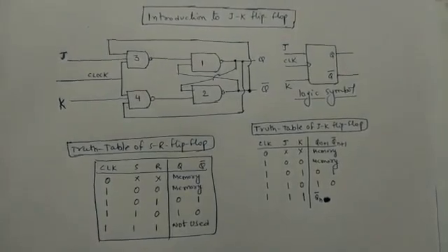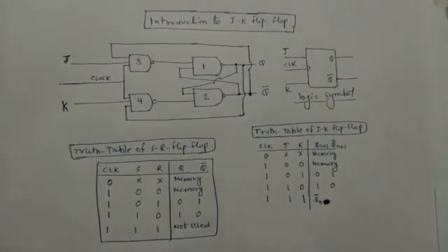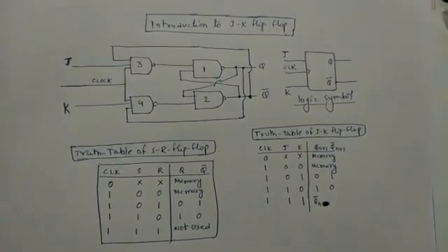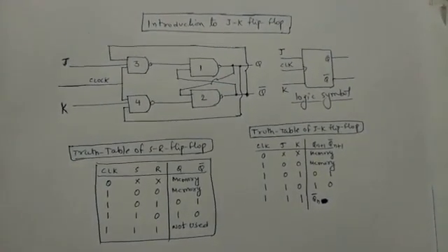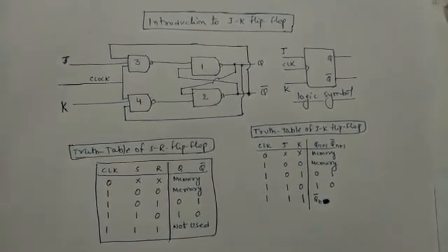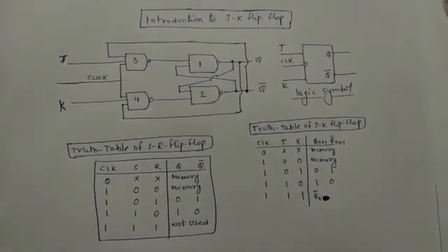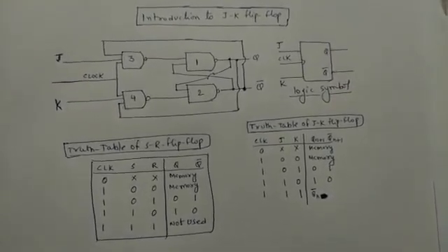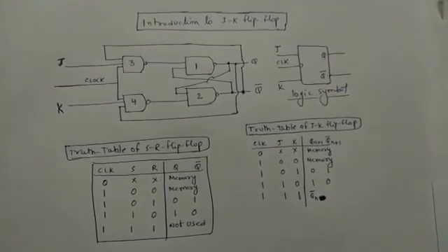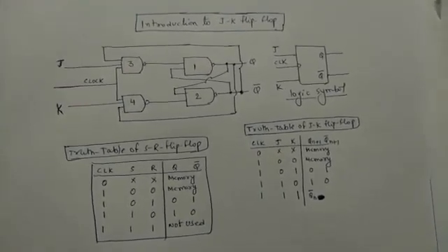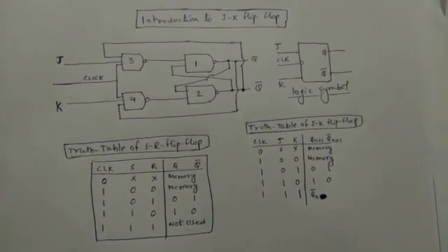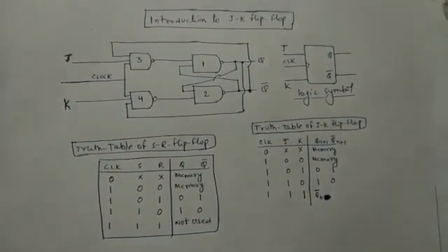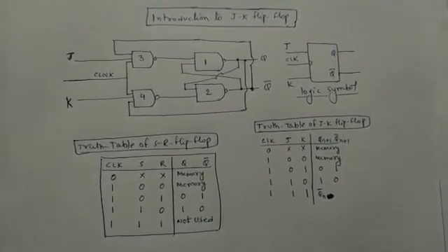We have already studied the SR flip-flop in detail in our earlier presentation, and we have noticed the disadvantage of SR flip-flop is mainly when both the inputs S and R are given as 1, because in that particular case it doesn't provide any outputs, and that becomes an invalid state in case of SR flip-flop. The same drawback has been overcome in the case of this JK flip-flop.